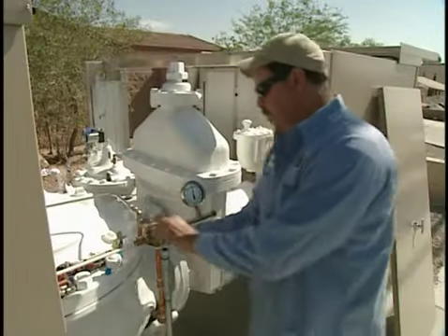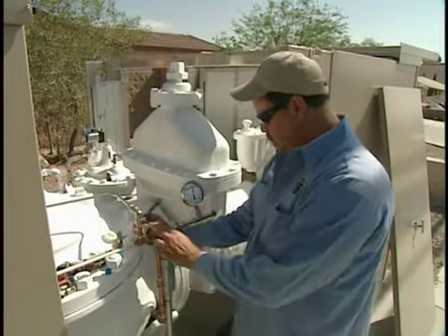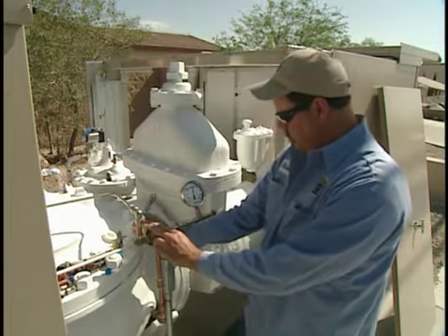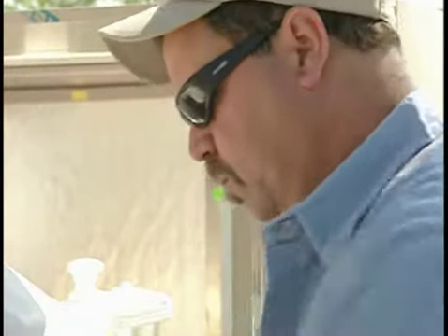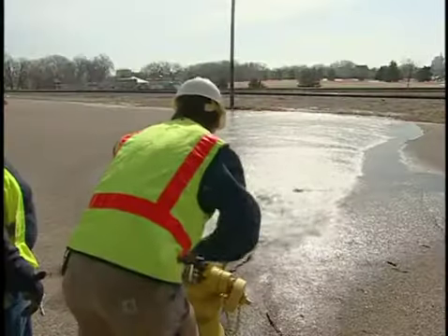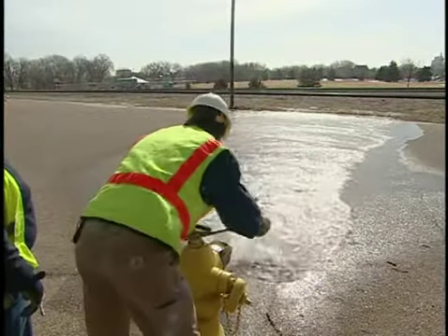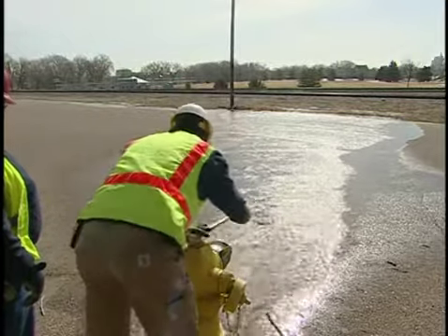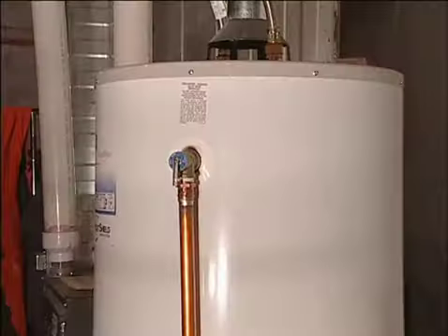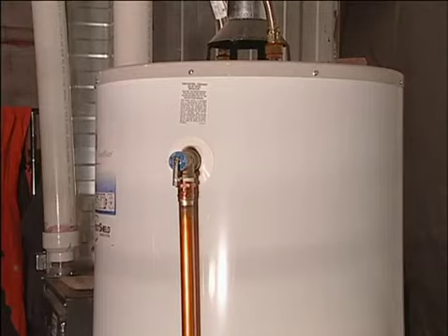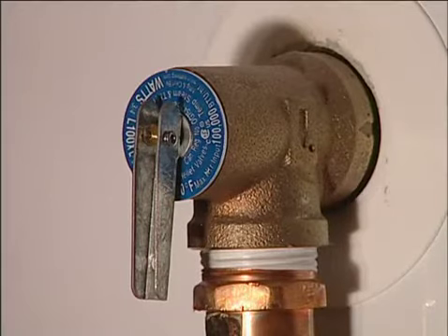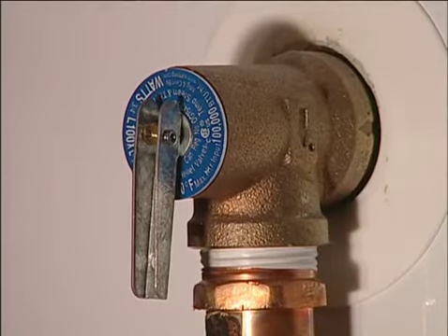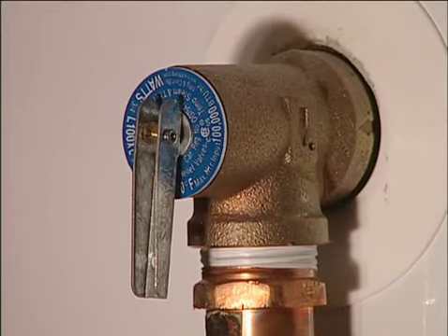A pressure relief valve is used to protect a distribution system from excessive pressures. High pressure in a system can often be caused by water hammer. Common causes of water hammer include starting or stopping a large pump and opening or closing a valve or fire hydrant too quickly. Plumbing codes also require small pressure relief valves to be installed on water heaters and boilers to vent excessive pressure so the tank won't burst.